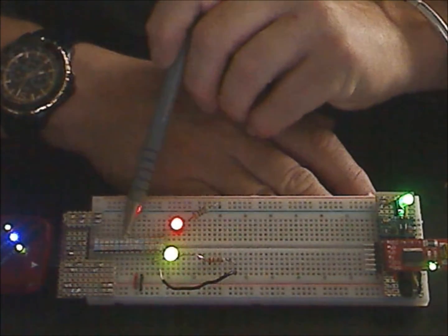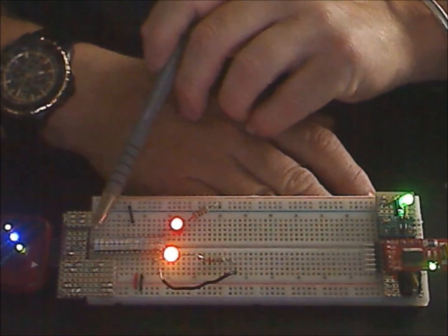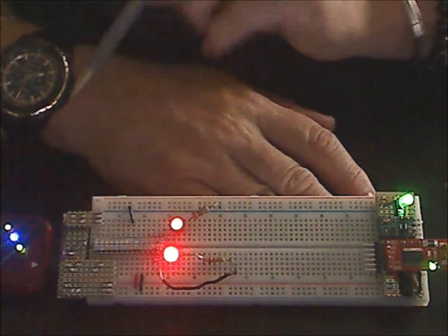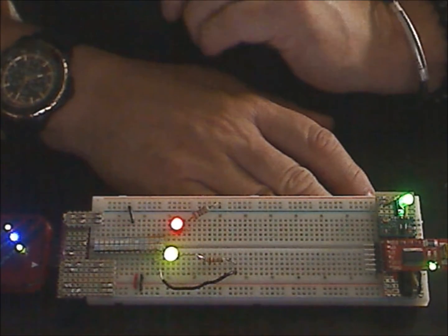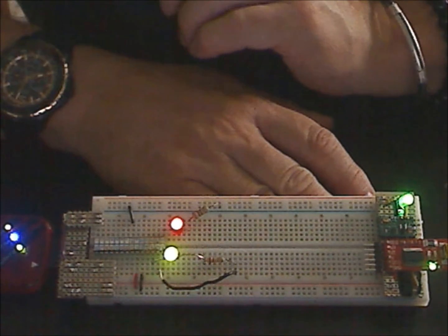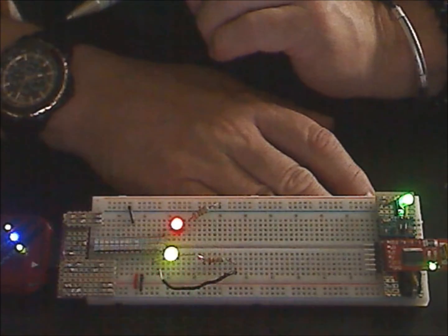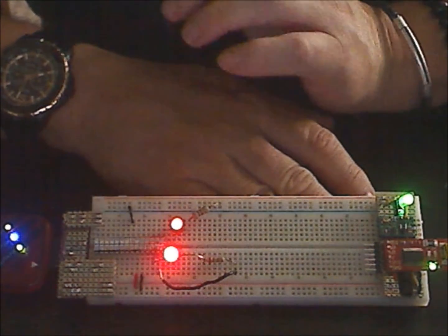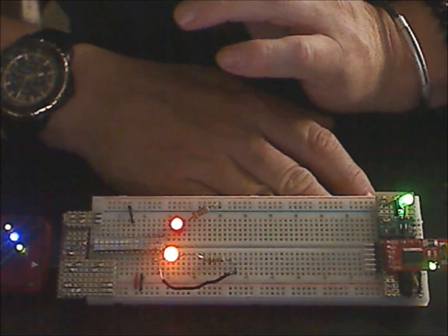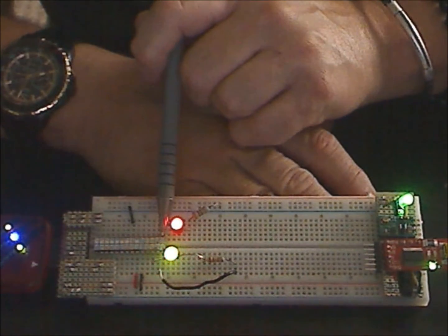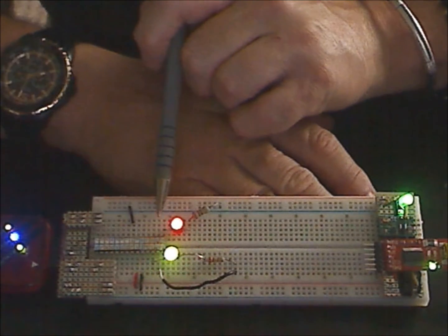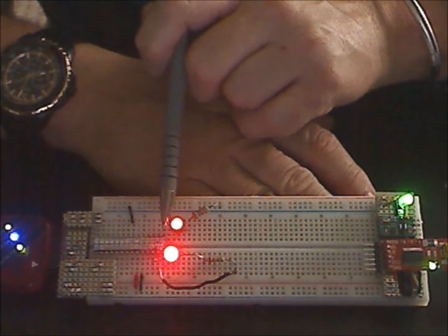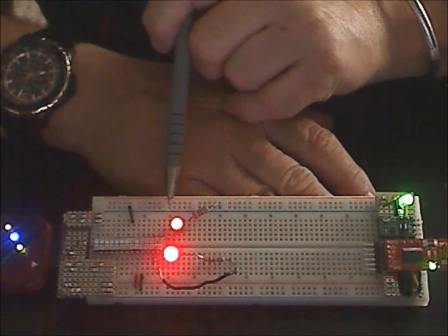I'm doing now, to light up LEDs. On your PIC, that's this guy right here, there are a whole number of pins. And many of these pins have a functionality called digital input-output. If you want to light up an LED, then you're using the digital output setting. And what the digital output setting simply says is if I'm using this pin as an output, do I want it to set it high, the 5 volts of the board, or low, the 0 volts on the board?